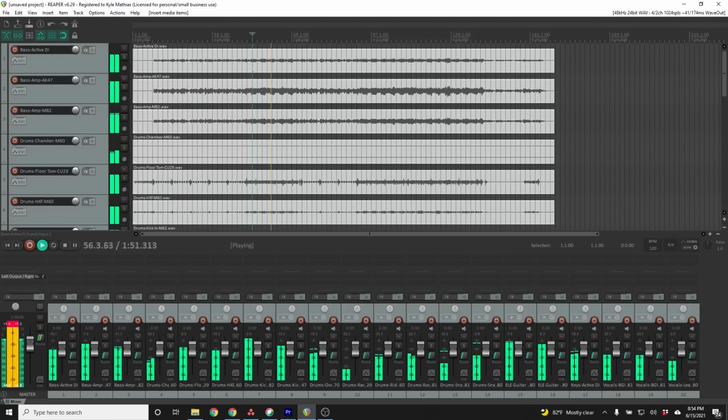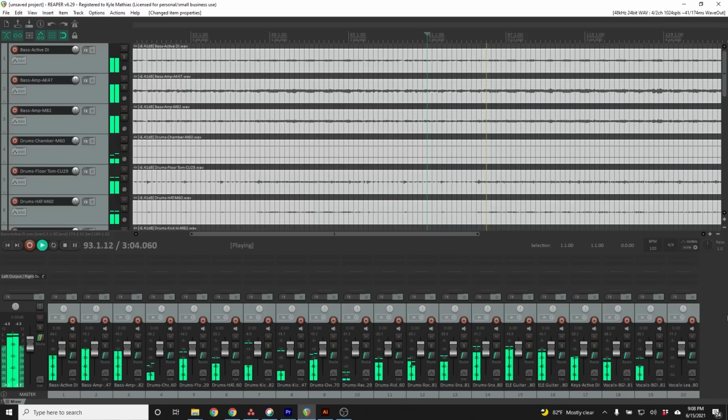It isn't just the individual channels that you need to worry about either. You may have encountered a situation where none of the individual channels were clipping, but the meters on the master bus were solid red. It's best to leave some headroom in your mixing system so that the combined level of all of the inputs doesn't exceed the limitations of the master bus.